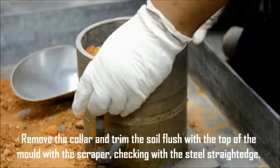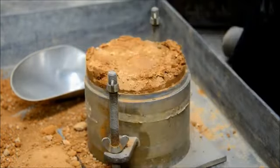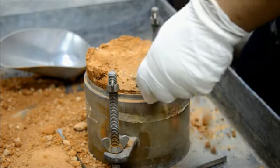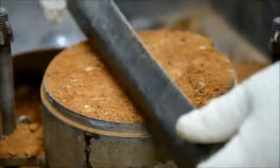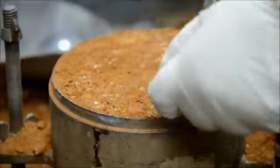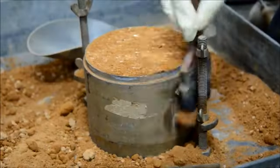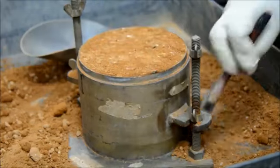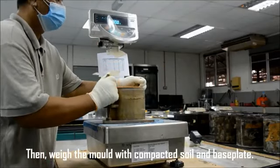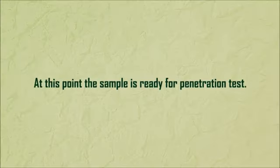Remove the collar and trim the soil flush with the top of the mold with the scraper, checking with the steel straightedge. Clean the mold and base plate. Then, weigh the mold with compacted soil and base plate. At this point, the sample is ready for penetration test.